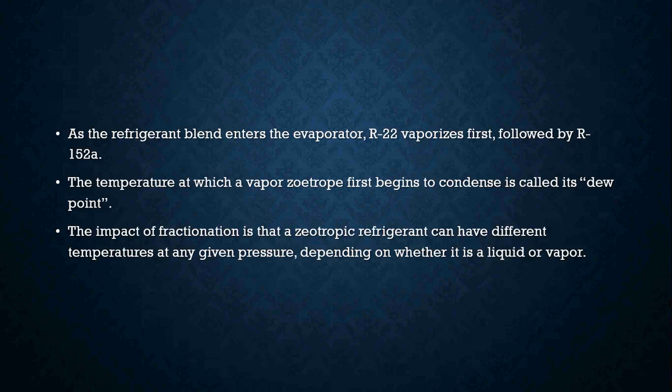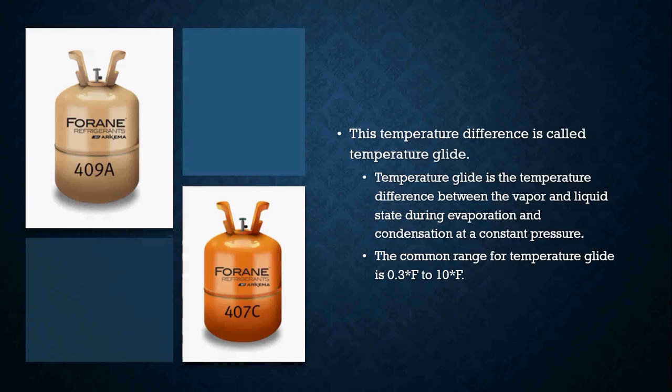If fractionation occurs, you're not going to achieve the correct temperatures or the correct pressures in your evaporator, your condenser, or even your metering device.